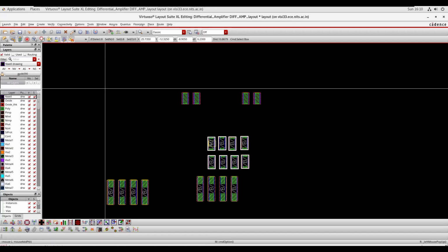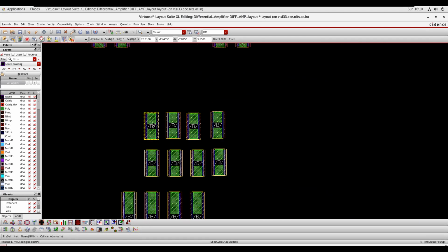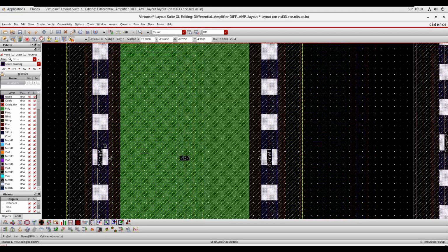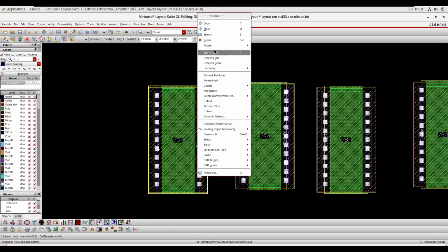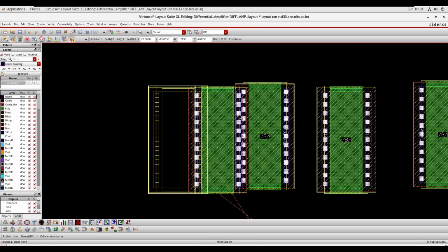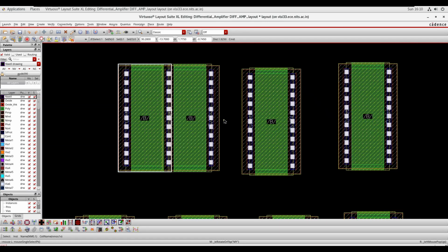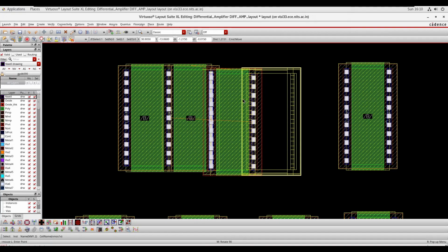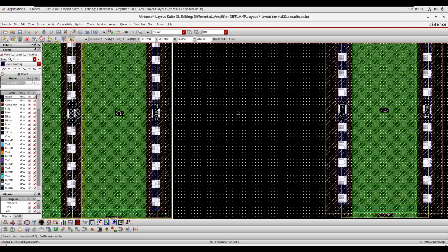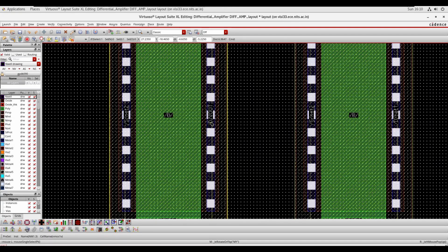So likewise you can check the alignment or arrange the pins accordingly. This is, you can see here, net 2. This is net 2. So you can flip this transistor horizontally and connect to net 2. It will align automatically. Next it is net 2 V out. V out is here. You rotate the V out. Now again here see net 2 is common. So in this way we can mark this is V out, this is net 2, this is net 2.